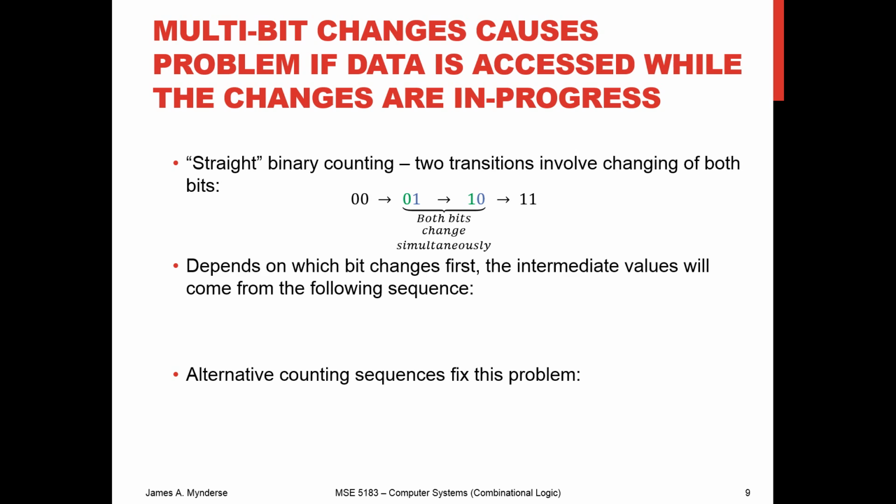One of them has to change first and then the other, because there are non-perfect propagation delays between them, and depending on how things are set up, it may even be intentional. So there's going to be a tiny time delay in there, on the order of nanoseconds, but it is still there, and there's still a possibility you're going to hit it and read the wrong value.